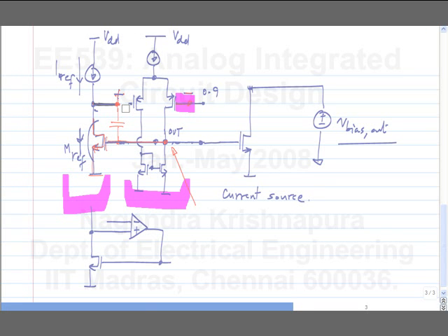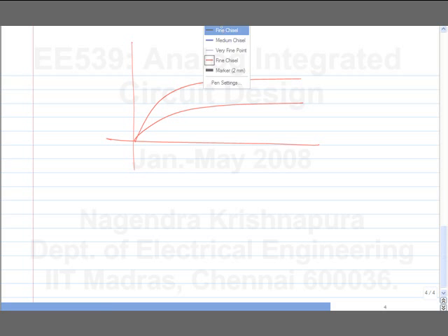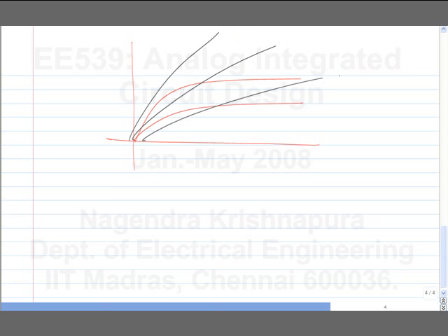We have designed some circuits in 45 nanometers, and there, if you vary the VDS by 100 millivolts, the current just goes all over the place. The characteristics of the MOSFET, we still draw textbook pictures like this, but in that I think it looks probably something like this. So there again you need accurate mirroring for everything.